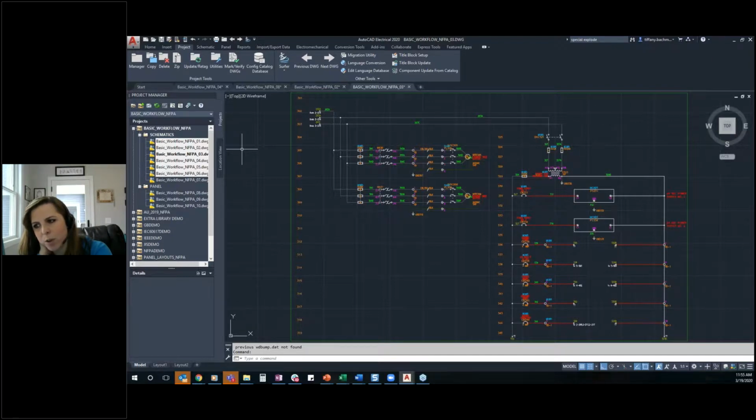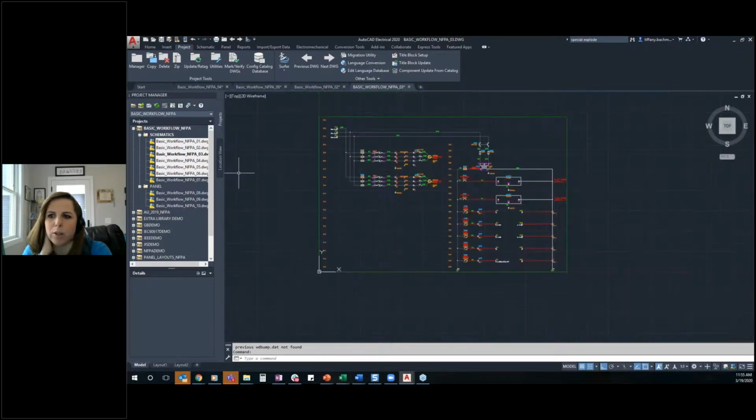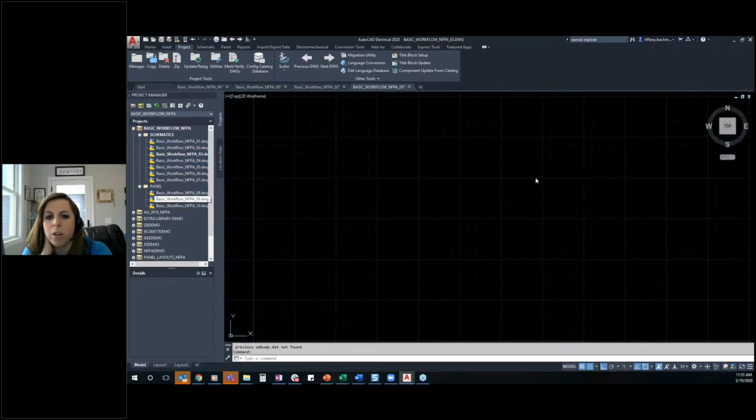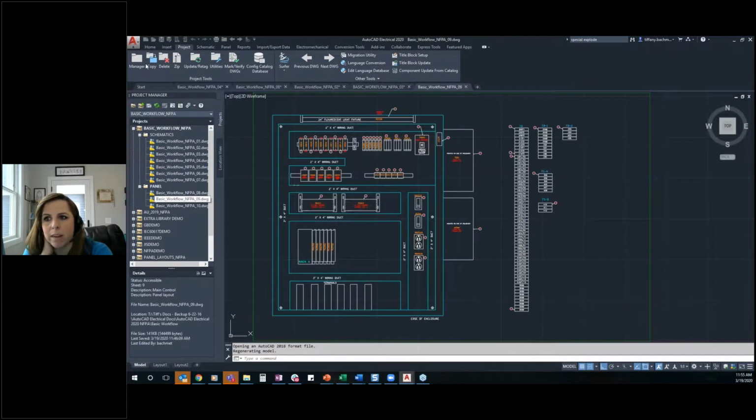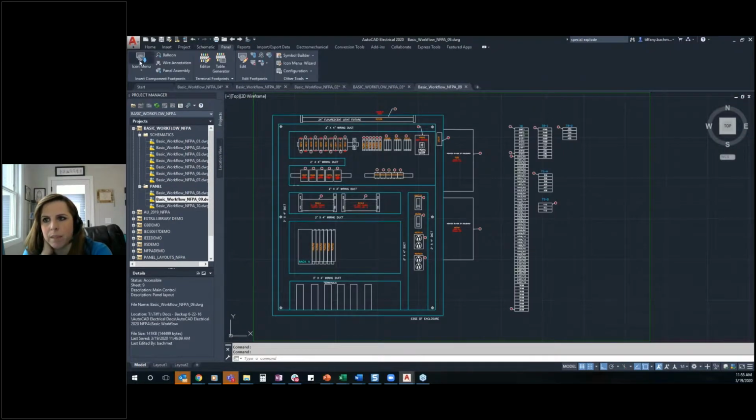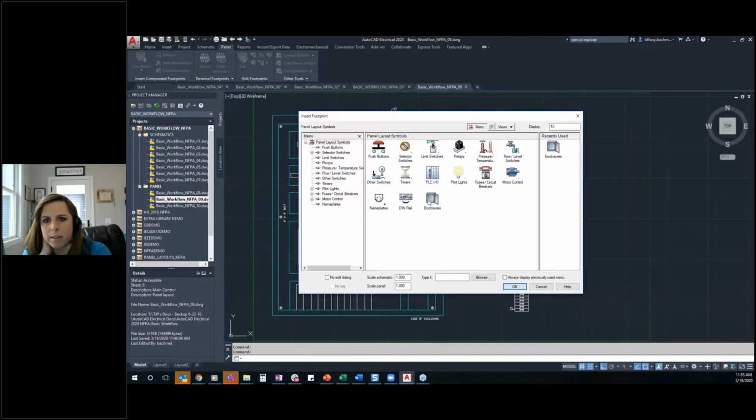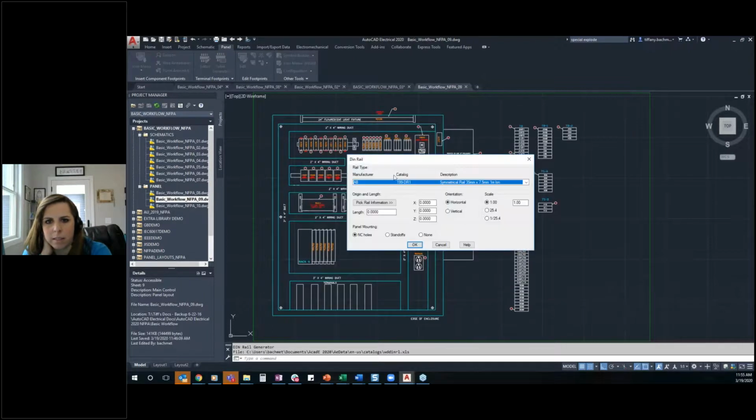So Lucas, how do you change the length of a placed DIN rail in the panel view after placing it already? So DIN rails, for anybody who's never seen them, look like this. And you can come in and choose any of your DIN rails, and then you can update. You can actually draw the length. You can say you want it to be 8 inches long, or you can just manually draw it.